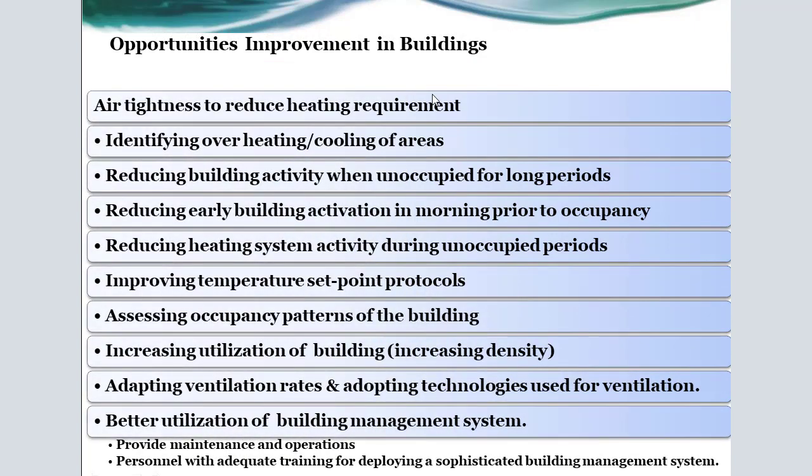Now, we talk about the opportunities of improvement in the building. As I said, we must pay attention to air tightness in order to reduce heating requirement, or even cooling requirement, and also identifying overheating or overcooling for areas. Sometimes we have excess heating or excess cooling in different areas in the organization.